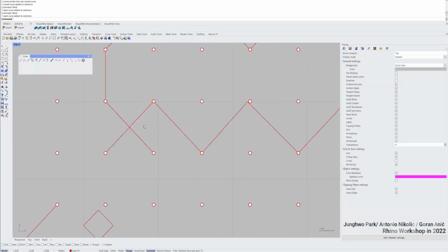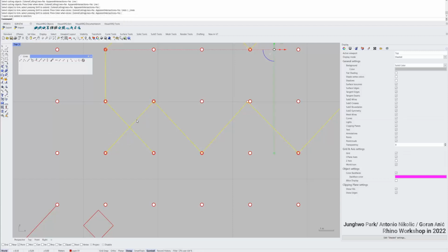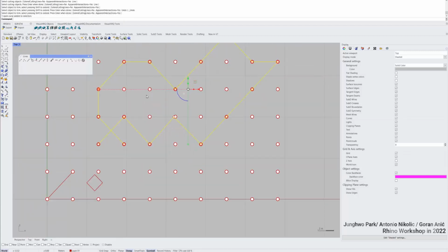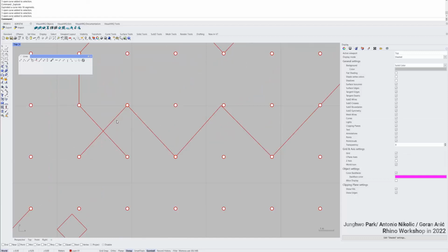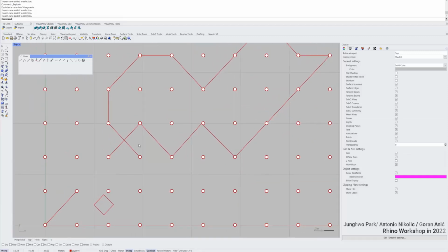All right, so I'm gonna use one of the AutoCAD commands, trim, so I can trim this. Sorry, before trimming it, let's explode it. In AutoCAD you can also explode the line. Now we have this polyline, 16 exploded single lines, and you can now type trim to trim, select. You can trim them basically.